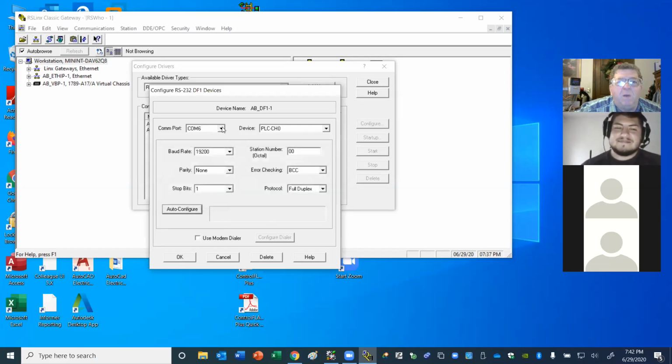Let's back it up, because a while ago it was 5 that worked. You see it? I had to unplug the cable. I unplugged the cable to the adapter and reseated it. So it turned out to be COM port 5, but I wouldn't have known. There was no way for me to know which one it was because on that hub, they're not labeled. And from the computer standpoint, depending on which USB port on the computer you plug into, that's also going to change the port numbers on that hub. So if it doesn't work the first time, you go down the list until you find the one that works.